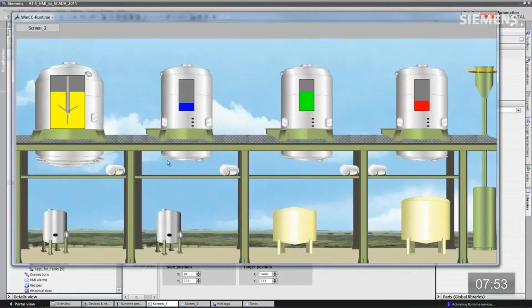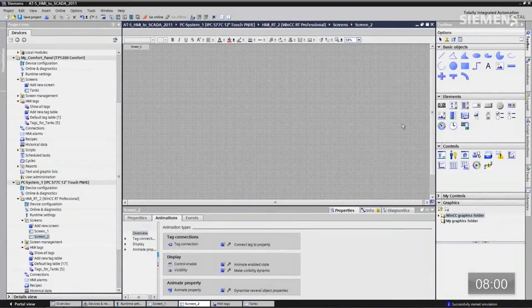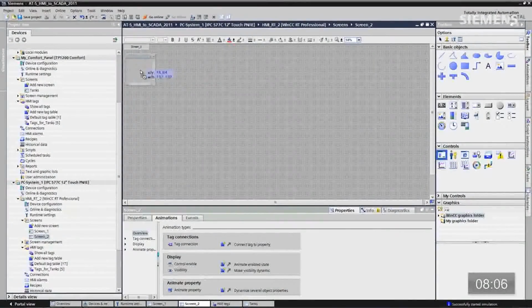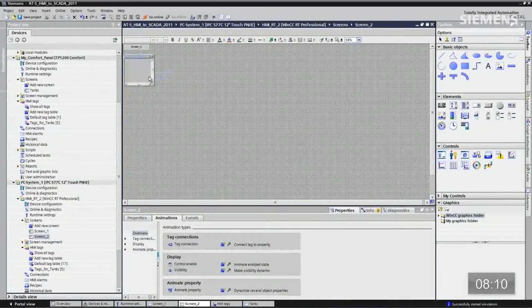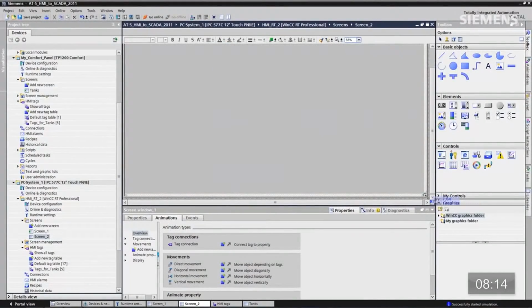However, there's one other thing I want to show you. How about actually doing a screen-in-screen or pop-up technology? So let's actually, okay, there's our screen. So let's go to screen 2 real quick. Double click on him. And let's go grab the control icon for this. It's called Screen Window. Let's drag it on. This is an ActiveX control. You can see a little alignment bars just like in PowerPoint. That way you can align your boxes wherever you want to and get everything sized right. Let's resize, refit them on to the screen.